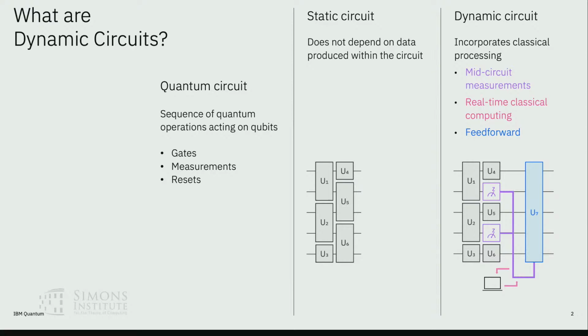What I want to note here is that at IBM, we have superconducting qubits. Superconducting qubits are great systems, which we can operate pretty quickly. We have coherence times of, say, hundreds of microseconds, and the gate time can be tens of nanoseconds to about 100 nanoseconds. Two-qubit gates and measurements are usually done in sub-microsecond. That means when you incorporate classical communication and classical calculation, you also have to do that in the same time frame, in a fraction of the coherence time. So doing dynamic circuits for superconducting qubit systems is quite challenging, but we have added this new capability of dynamic circuits.